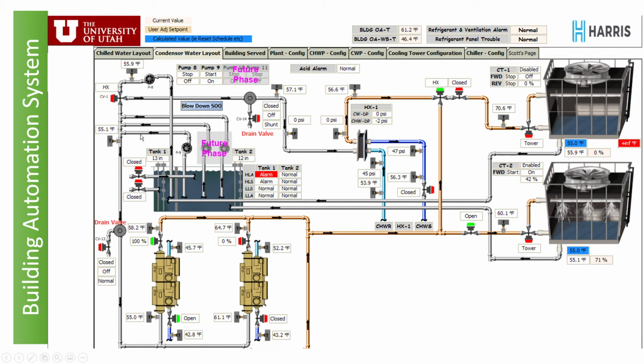So those pumps are pumping water into the condenser side of the chiller. And then it simply goes back out to the cooling tower. That's it. But you're like, wait, what about free cooling? So the pumps do have the option to send water, there's our three-way valve, over to the plate and frame heat exchanger.